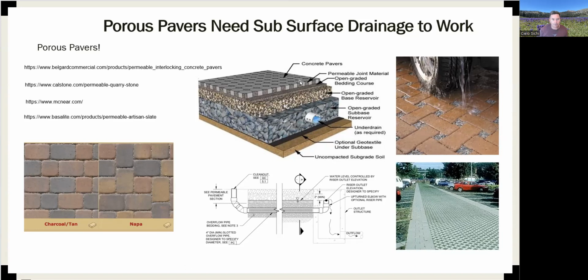This allows water to flow directly through that and then through a graded sand and then through an open graded base reservoir into an open graded sub-base reservoir. This is relatively intensive, but any good paving or concrete and masonry company can put these systems together for you.